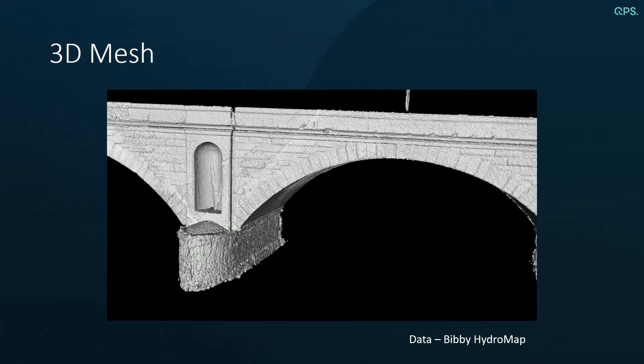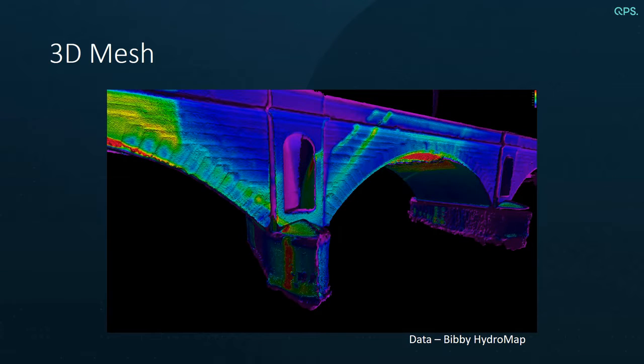Going further and using a 3D mesh, we can see that fine details that were obscured even with the eye-dome lighting technique are now visible. Furthermore, by having a complete and constructed shape, we can then do additional analysis such as density or volume calculations.